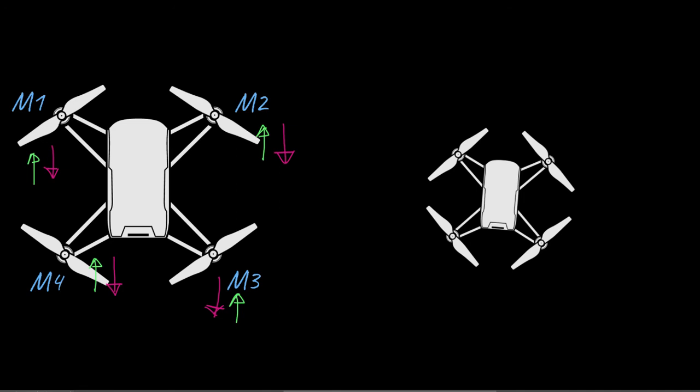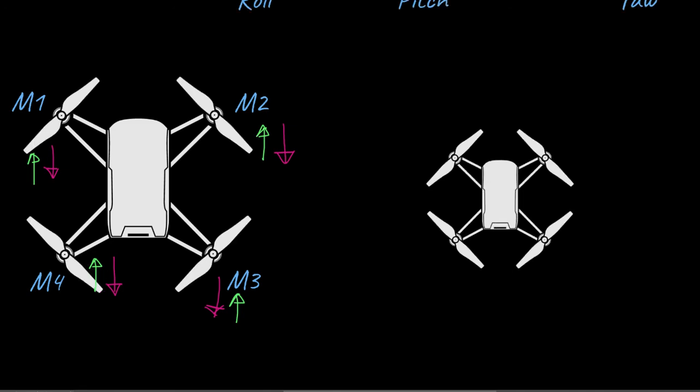So for example, if you want to make the quadcopter more stable and you don't want it to rotate across its axis, you need to put the propellers rotating in different directions, the opposite propellers moving in one direction and the other opposite propellers moving in the other direction. If you don't do that, then the quadcopter will suddenly start to have a rotational effect, and it might start spinning across its axis. It can spin in the clockwise or anti-clockwise direction, and we don't want this to happen.